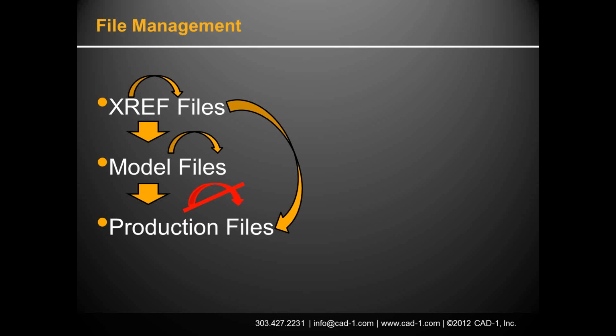And the reason I recommend that is because, well, Civil 3D is a resource hog. Every time you regen the drawing, all the labels have to go through and figure out, hey, do I need to update or not? And if you have a lot of labels, even XREF labels, that can take a very long time to do. So I highly recommend when you're working in a drawing, think about it. What do I need in this drawing in order to create this drawing? Well, only bring that stuff in.